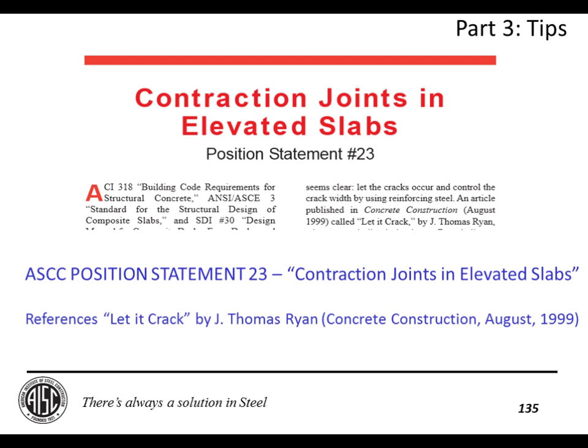What the American Society of Concrete Contractors promotes, and I agree with, is in Position Statement 23, they essentially say that rather than putting in contraction joints, you should take the effort and money and put it into providing more distributed reinforcement to try to keep the cracks that do form from opening up, as opposed to just putting in defined contraction joints.